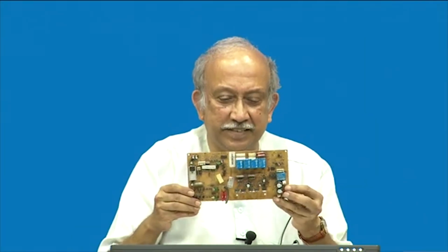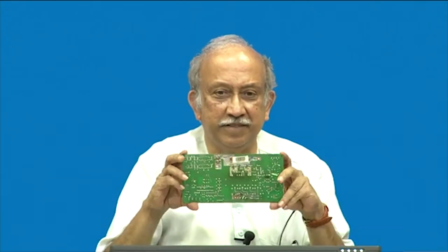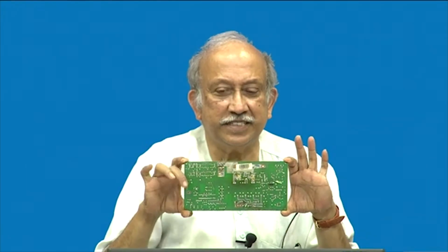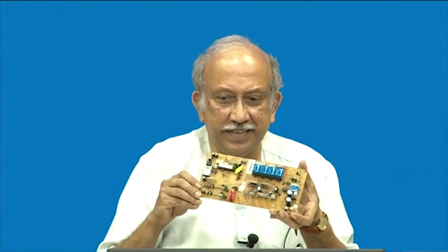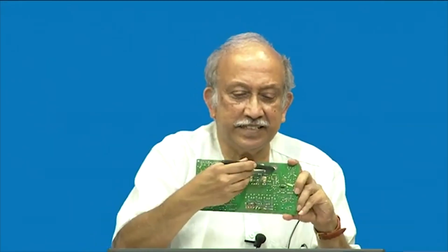While it does not look very attractive, the reality is this whole thing has been mounted with 4 holes on one side, and again coming back to the features, on one side at one corner here we have a heat sink, and there are mounting holes on the heat sink. There are 2 mounting holes, and the heat sink goes, and then all these power devices are supposed to get assembled on the heat sink, and they share a common base which has to be fixed here. Now this is where the process planning also comes into the picture, saying do we first mount all these things and then try to push them inside? Alternately, do you push all of these things inside and do everything, and then how do you assemble the screws and all that? So for this, standard practices are there, and standard jigs and fixtures are there.